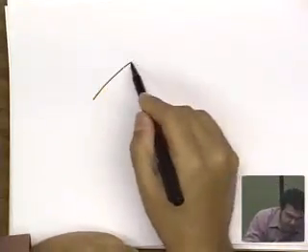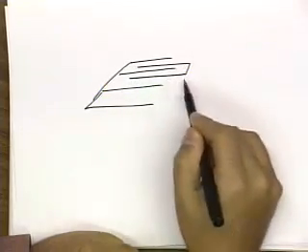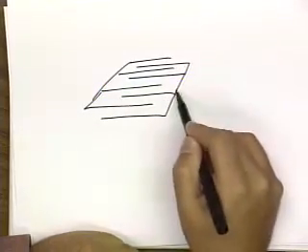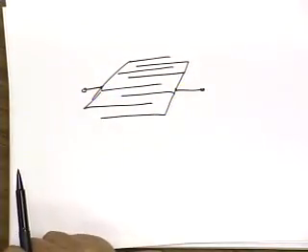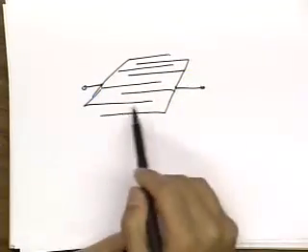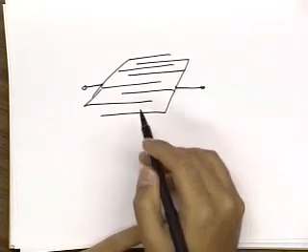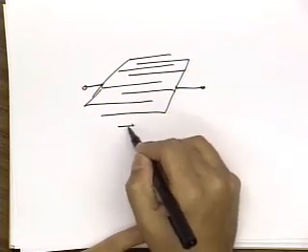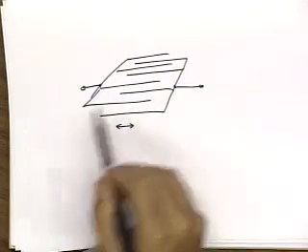So the idea is that you're going to build a structure like this that has these fingers, and this is going to be a polysilicon structure. So in fact, this is really just a capacitor, right? And the capacitance is a function of basically the spacing between these fingers. If you have a displacement in this direction, the capacitance will change a little bit, because it's mostly lateral capacitance here.